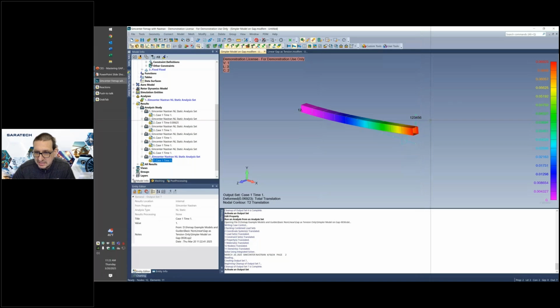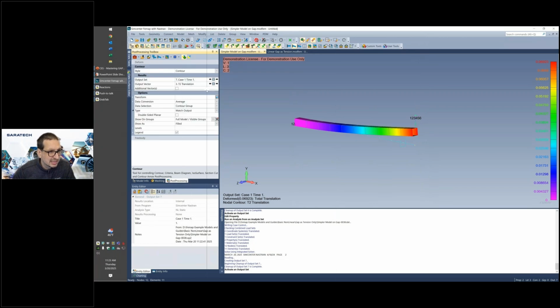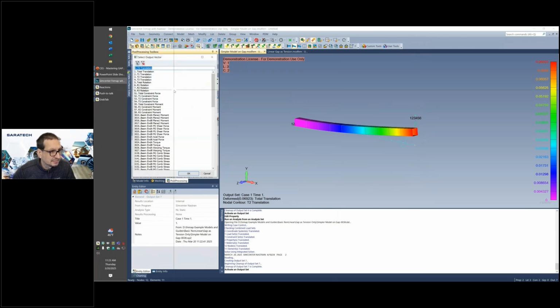Now remember, as the gap element gives, or as our model gives, because that is a spring force, as our spring relaxes a little bit or doesn't fully contract or expand, it will actually reduce the final force applied to our model. But I believe in this case here, because my beam is so thin, it's only a 1/2 inch bar and it's 10 inches long, it is pretty close to giving us that value there.